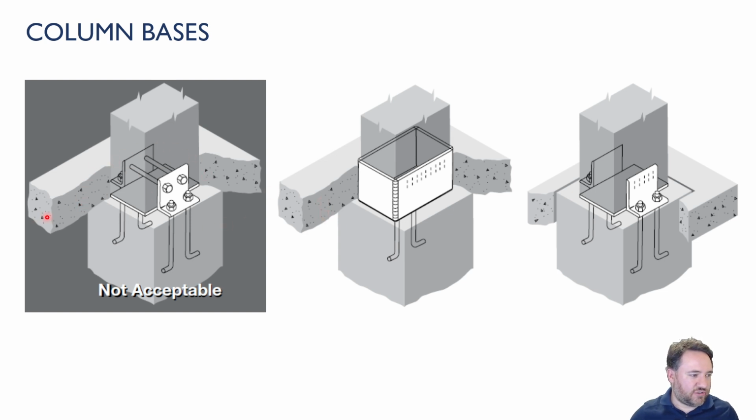So one option, if you are restrained geometrically, like you need this column to come down a certain depth, is to provide this collar. Of course, another consideration if you're doing a collar like this is you have to provide some space for water. If water gets stuck in this column, it has to be able to flow out. So you can't make a closed collar on the bottom of a steel column, because inevitably water is going to get in there, it's going to get stuck, and then it'll rot your column. So you need to provide always some kind of weeping space to allow water to get out. So this is probably not a great deal.